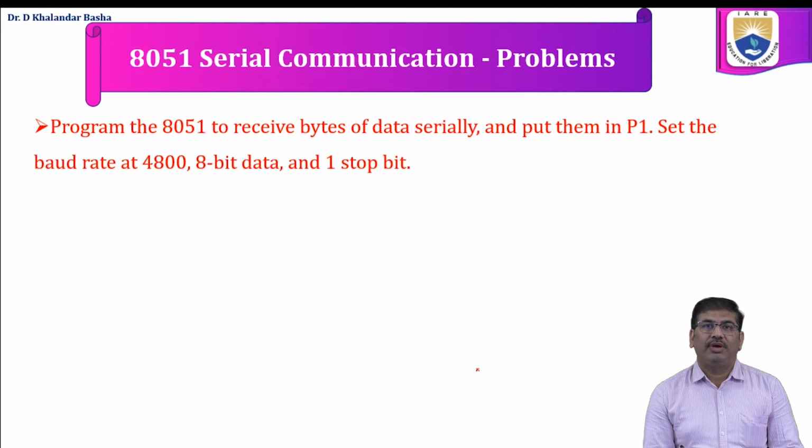Program the 8051 microcontroller to receive bytes of data serially. Put them in port 1. Set the baud rate at 4800 for asynchronous communication with 8-bit data and 1 stop bit.